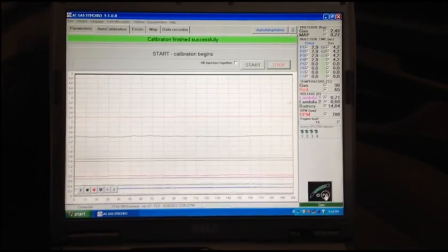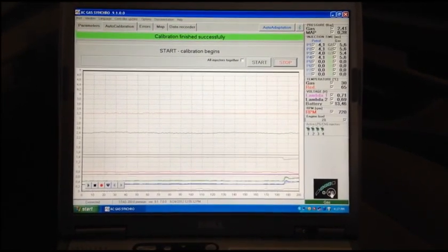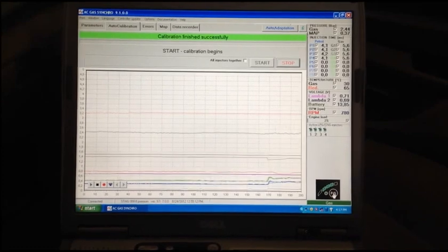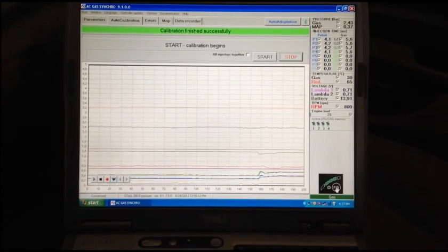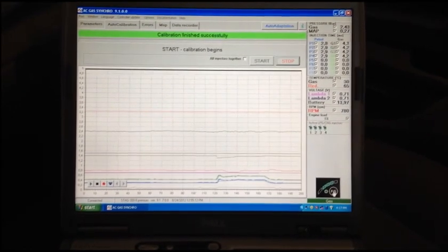Yeah, like I said, when you're looking at that, make sure every accessory is turned off, because if you turn the air conditioner on, the compressor kicks in, the pulse goes up, and you're wanting to see what it's like under the minimum load of the engine, that it's still going to be able to predictably and smoothly idle.